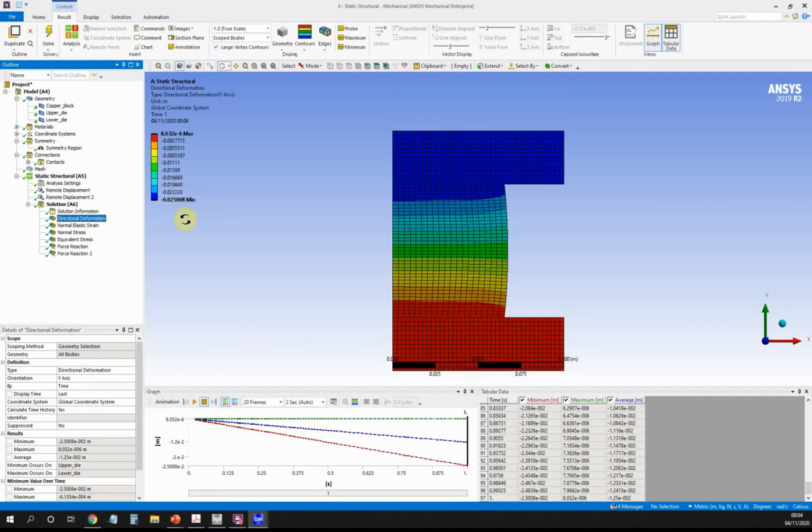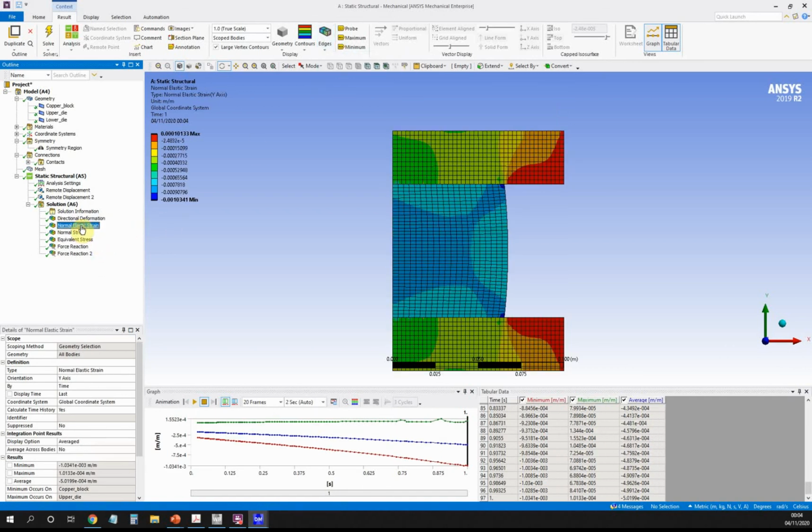So again, there's my 25% reduction as I'd expect. Again, it's going to show the undeformed wireframe, so I can see the original shape and the new shape I have. Again, the contours are looking a bit better there, more like what you'd expect. And we should see, yeah, exactly. I was a bit puzzled the last time I was looking at the values for stress and strain, wondering why I didn't get this kind of shape in here, because that's a characteristic shape that you obtain in this analysis for stress and strain results.